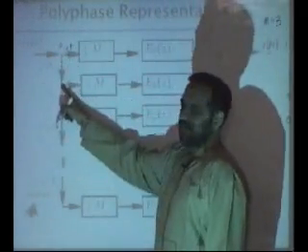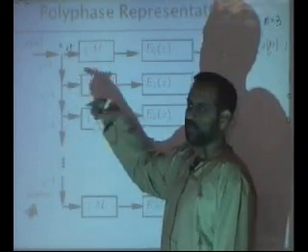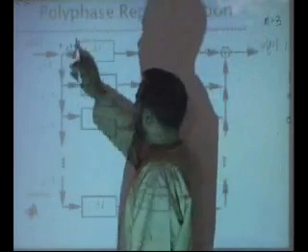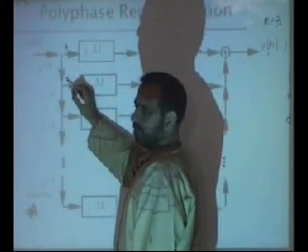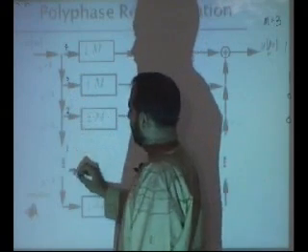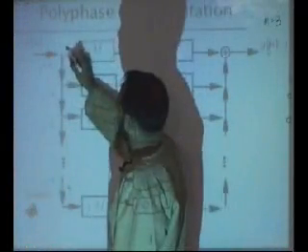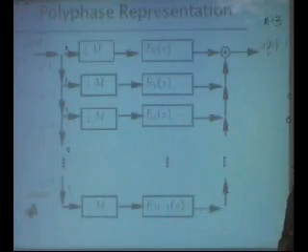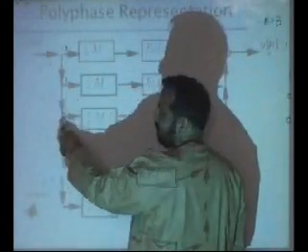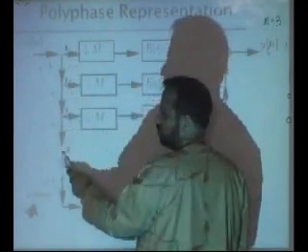Here is a delay. So once I bring 0, I need to have 1, for example, a delayed sample. If I started from 4, let's say, if I have 4 here, I will have 3 here, 2 here, 1 here, and 0 here. For example, I should start from 3 in fact. Sample 3, sample 2, sample 1, and sample 0, right? This is how it will work. Because this is a delay, the previous sample a delay, previous to previous sample a delay, previous to previous to previous sample. So 1, 2, 3, 4 branches.